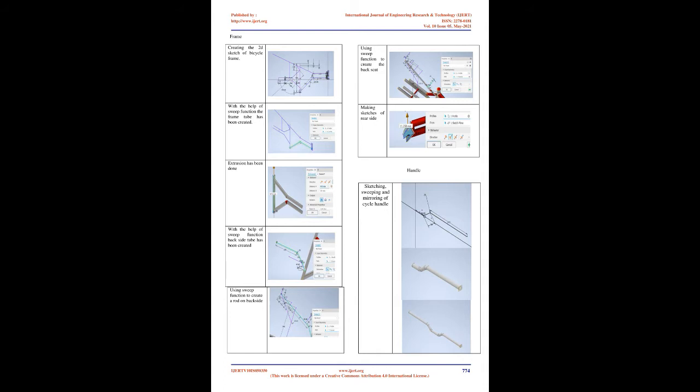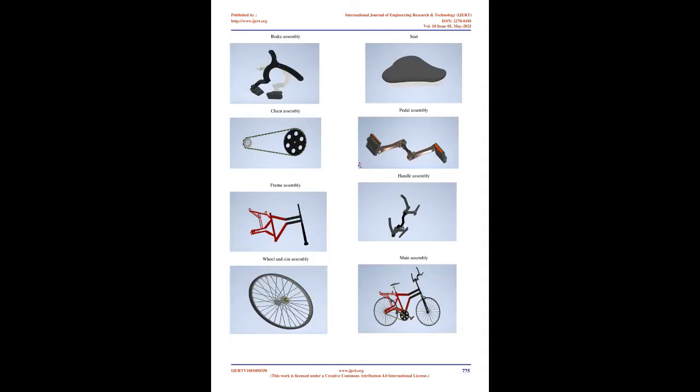To run a FEA simulation, first a mesh is generated. This is a way of transcribing a 3D object into a series of mathematical points that can then be analyzed. The density of the mesh can be changed based upon how complex or simple a simulation is needed. Calculations are run on every single element or point of the mesh and then combined to form the general outcome